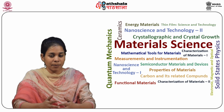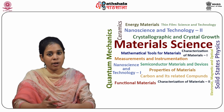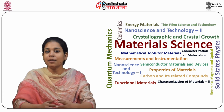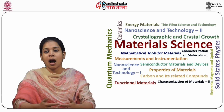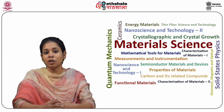The functional ceramics are the advanced ceramics used for electrical and electronic, magnetic, optical and related applications, while the structural ceramics are those in which mechanical properties such as strength, modulus, toughness, wear resistance, hardness, etc. are of primary interest. Almost 70% of advanced ceramics manufactured today belong to the functional ceramic category.